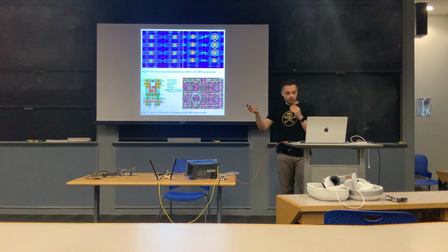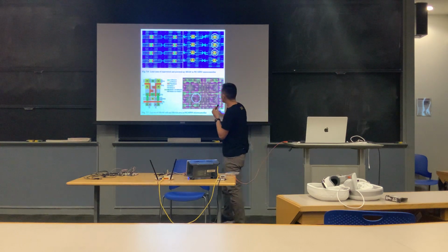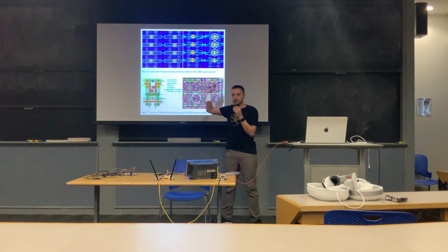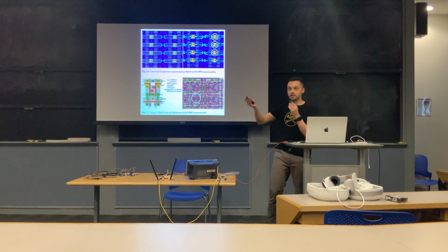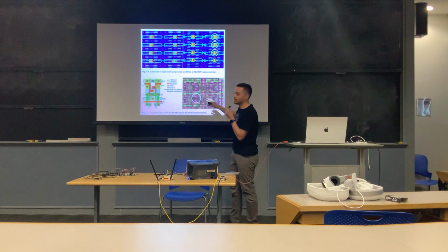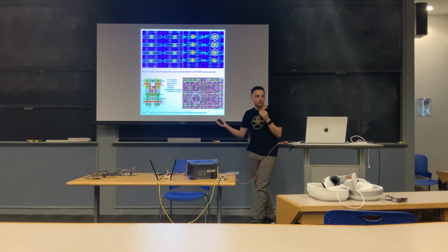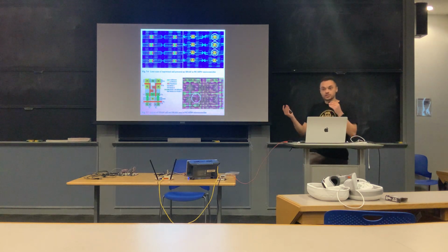And so here's another photo of what optical imaging might get you. So this is a laser scan of some SRAM. You actually see visually that if you scan the chip while it's in action, you can kind of read out some of the bits. You can see what the state of the SRAM is just through optics alone. And here's another photo of some layout of those SRAMs just from a VLSI perspective of what the chip might look like. So you can do a lot of really cool things with physical access to chips.